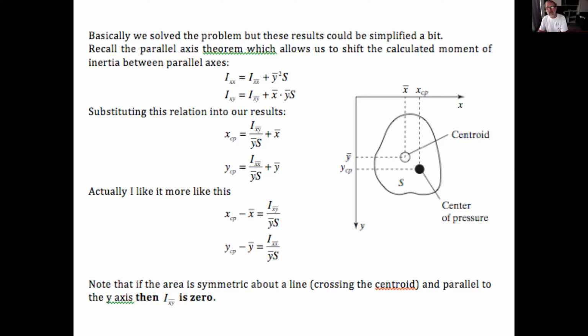So let's go back to dynamics. So you have these coordinate systems. Remember, y goes along the depth coordinates on the surface. And then this is the centroid of that area of interest. So this is the area of interest here, and it has a centroid, no problem. We calculated it. And now we're trying to spin it about these axes. But if you look at most of the handbooks, they will give you moments of inertia about the centroid.